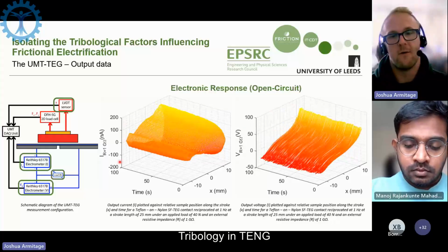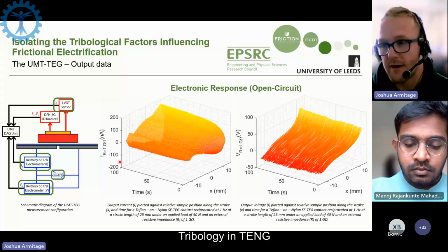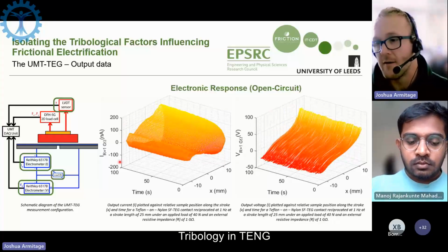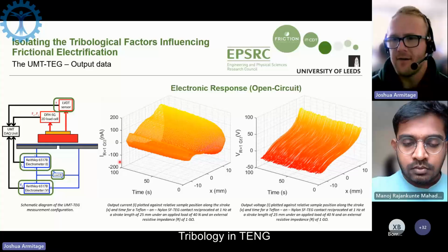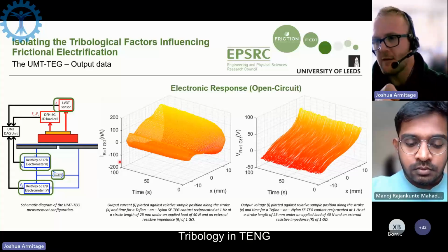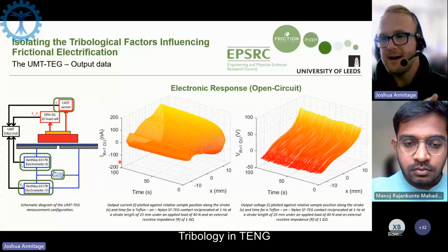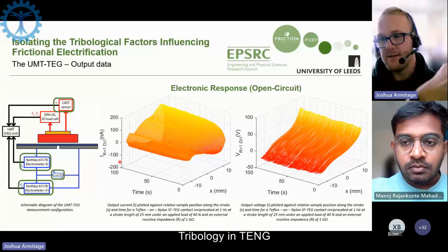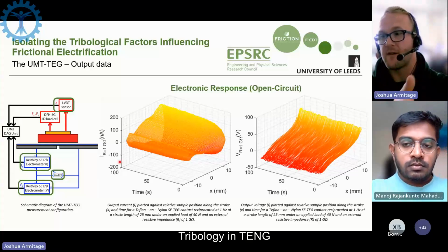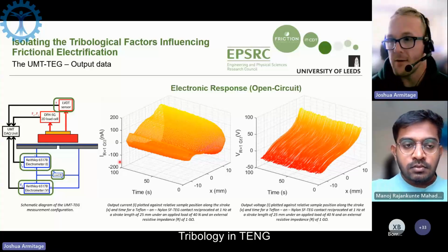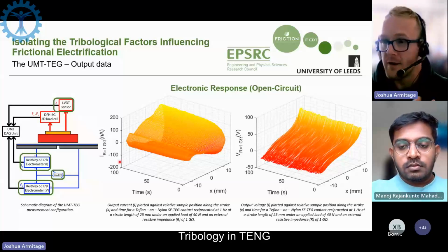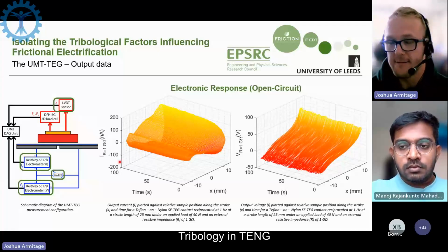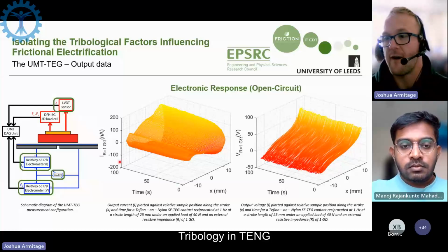When we increase that resistance, though, we start to see what things are like in the open circuit realm. The voltage now directly corresponds to the position of the block over time, which makes sense because if you have an infinite resistance, the potential between the two electrodes will directly depend on where the static charges are along the stroke relative to the position of the two electrodes. And the current we measure is just a matter of how quickly that electric potential is changing. So the faster the block moves, the higher the current we measure.